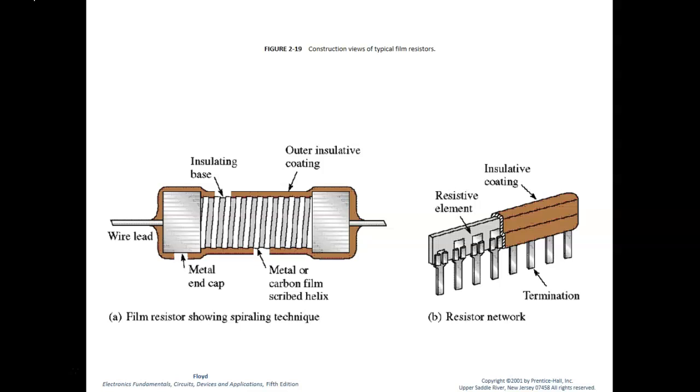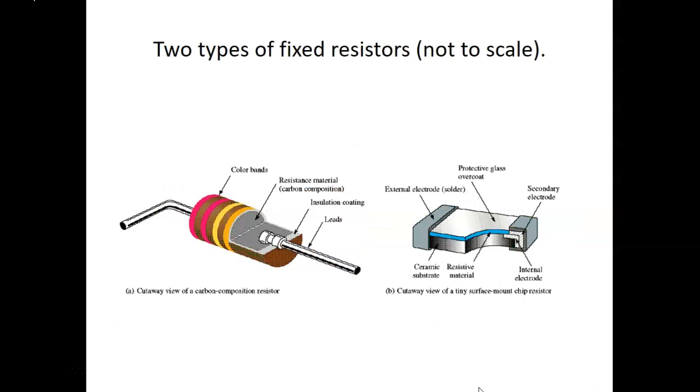Resistors are multi-directional. In other words, it doesn't matter which way you plug it into a circuit, it still works. There is no forwards or backwards bias to these. They work both ways. However, I will point out on the color bands, those can only be read one way. We'll talk about that in a minute.